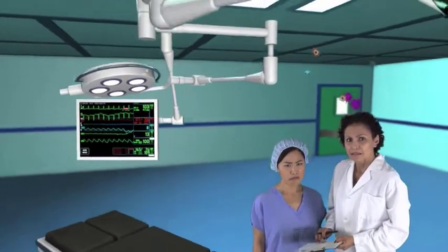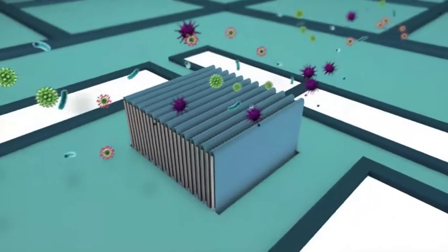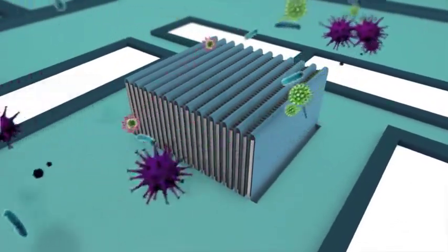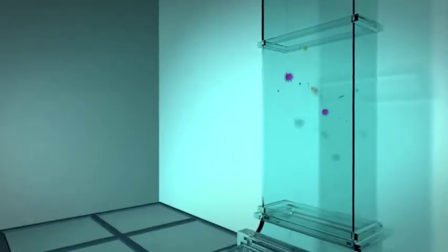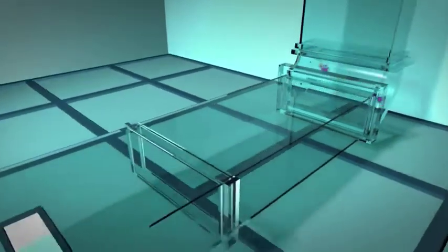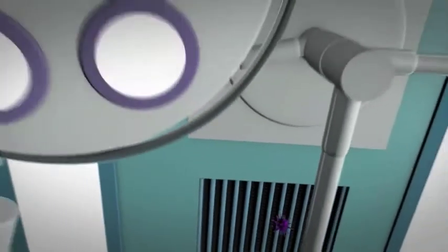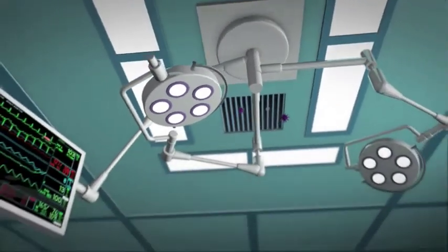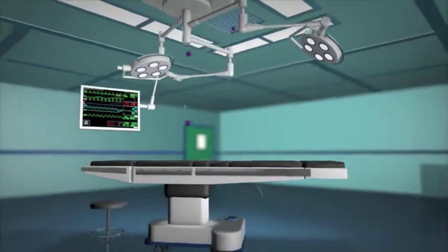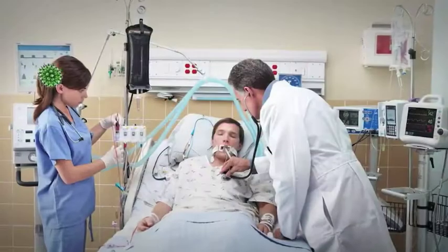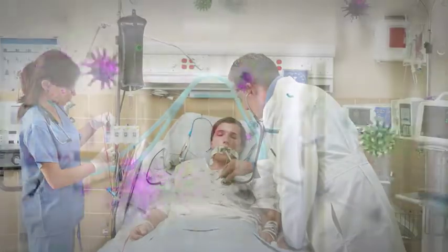Hospitals feel protected by the use of HEPA filters that block up to 99.97% of particulates. However, 1 cubic foot of air typically contains 100,000 microparticles. With air traveling at approximately 800 feet per minute through a 24-inch square duct, we have 80 million particles. So, on average, 0.03%, or 24,000 of the particles per minute, might break through the HEPA filter. If only some microorganisms break through, they can infect the patients.